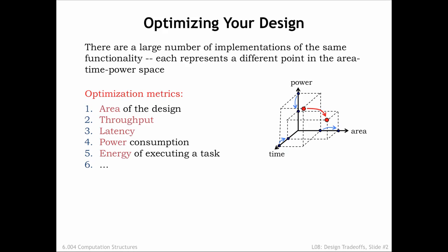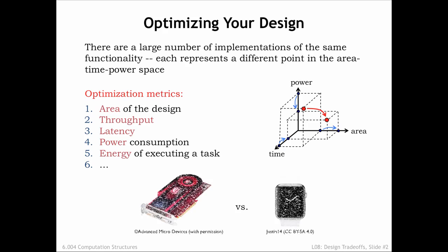Making trade-offs correctly requires that we have a clear understanding of our design goals for the system. Consider two different design teams. One is charged with building a high-end graphics card for gaming, the other with building the Apple Watch. The team building the graphics card is mostly concerned with performance, and within limits is willing to trade off cost and power consumption to achieve their performance goals. Graphics cards have a set size, so there's a high priority in making the system small enough to meet the required size, but there's little to be gained by making it smaller than that.